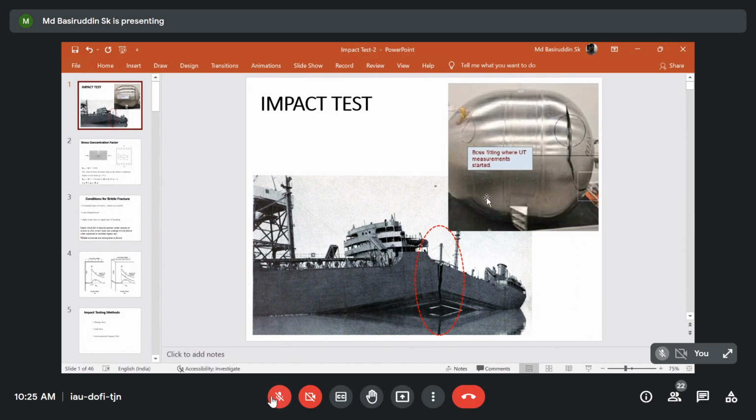So though we are studying the situations of impact loading conditions where the material behaves differently, we will also study how, during different types of loading, the material behaves and fractures from ductile fashion to brittle fashion. We already studied during the tensile test that if you apply the tensile loading, the materials generally separate into two pieces under ductile fracture manners.